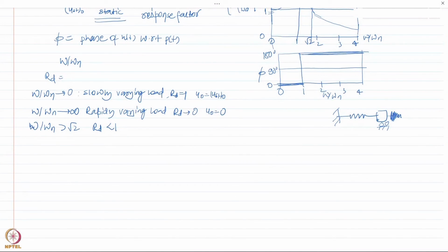For example, let us say I have a static system, a building just sitting there. Would I not be happy if I apply some force or frequency on my structure, and the response becomes less than the response it would have if the load had been applied statically? I would be very happy, right? That depends on the applied frequency, and this property is utilized in vibration isolation. We will come back to it later.